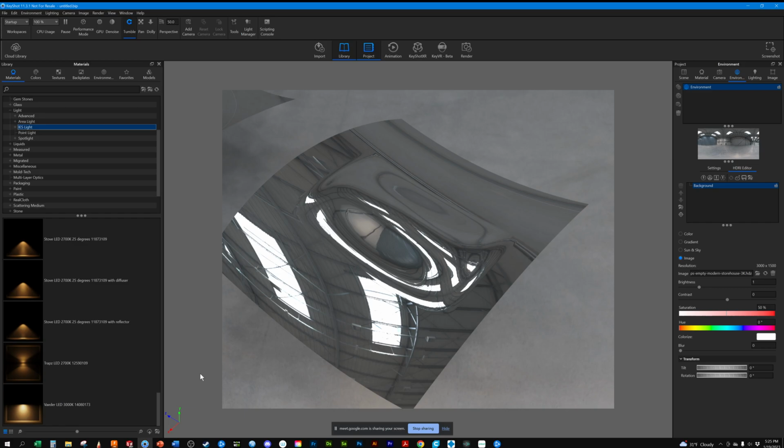And then it really, really sucked because they're like, what are you guys thinking about the finishes? And I was like, well, here's what you should do. This part should be polished and then have matte black on here with a light vapor texture. And they're like, yeah, we tried that, but we can't do it. Why do you think they can't get a nice matte black finish on a cast black part? It wasn't designed for it. No. Because their vendor. The mold finish isn't smooth enough.